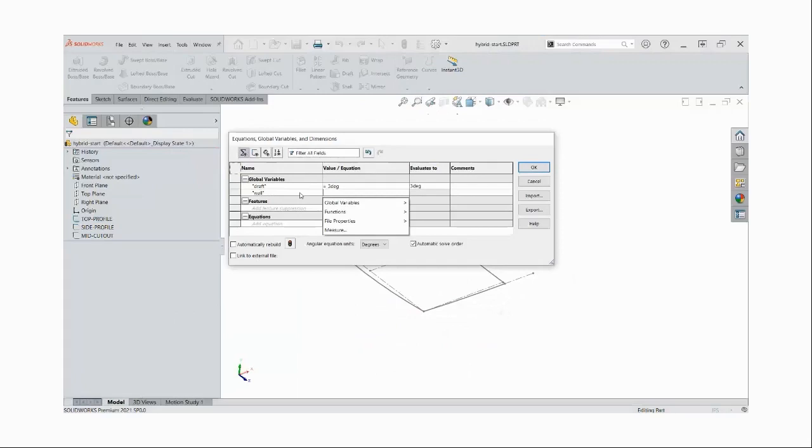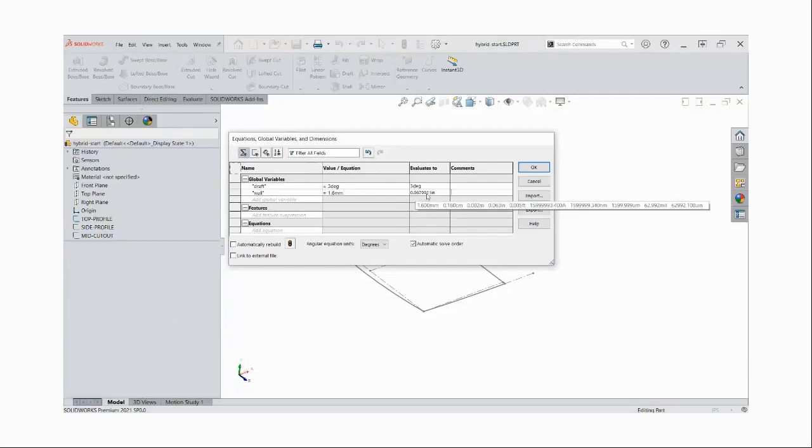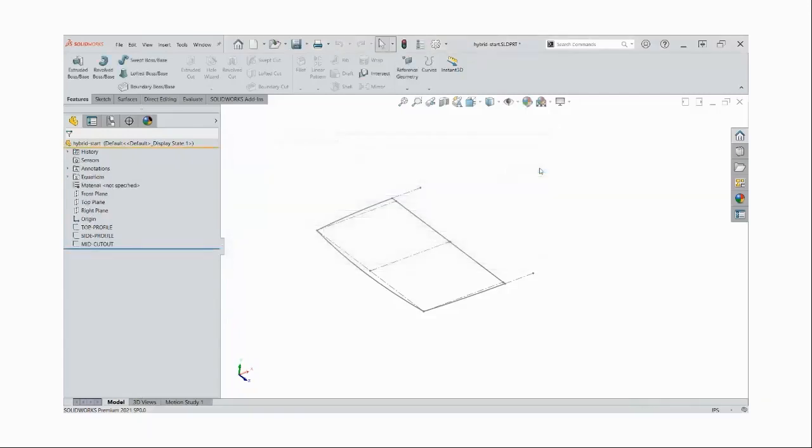So sorry, but I'm going to type in here 1.6 millimeters and hit tab, so that gets converted to the appropriate inch value. If you don't type in the units in an equation, then SOLIDWORKS assumes that it's just the units that are set in your document, so it would think actually that that's 1.6 inches. So I'm going to click OK and accept that. Those are just variables that live up top here that I can re-reference in this equations folder.